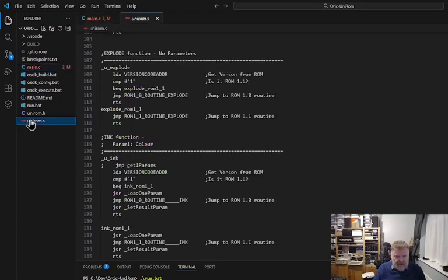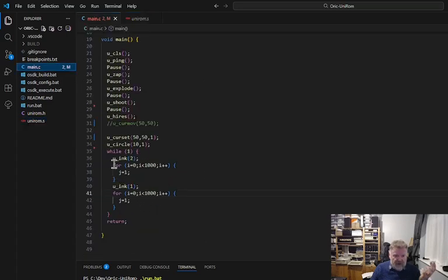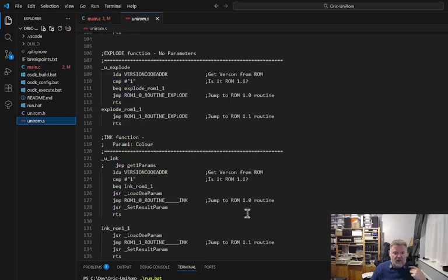So what that does is there are some additional methods to take 1, 2, 3, or 4 parameters off the stack and load them into a very special place in page 0, which contains the parameter block, up to 4 parameters, I think, that is used by those ROM routines. So that's how you pass data in. So OSDK will compile it all, and when you run it here, that data is put on the stack, and then that's read out. So let's have a look.